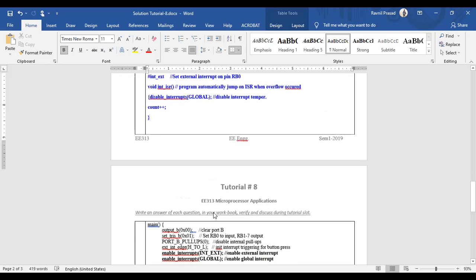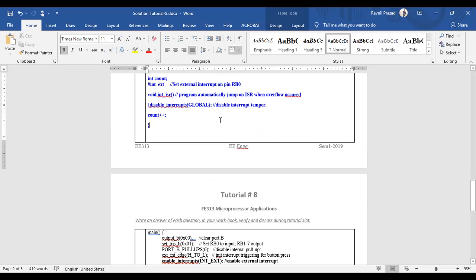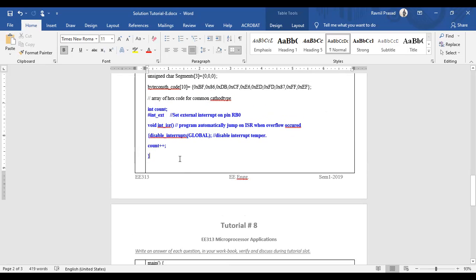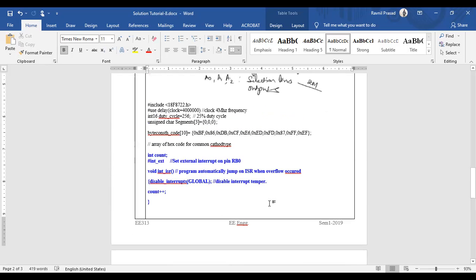proximity sensor. So what happens when we go into the external interrupt loop? We need to count, right? So basically, when we are counting, we are increasing the count. So we have a variable count that needs to be increased, right? So we enter the external interrupt loop whenever there is an interrupt, right? We need to define the function that will be a void function, right? Definitely, this is a void function that gives the ISR. I mean, it is named as int ISR, right?